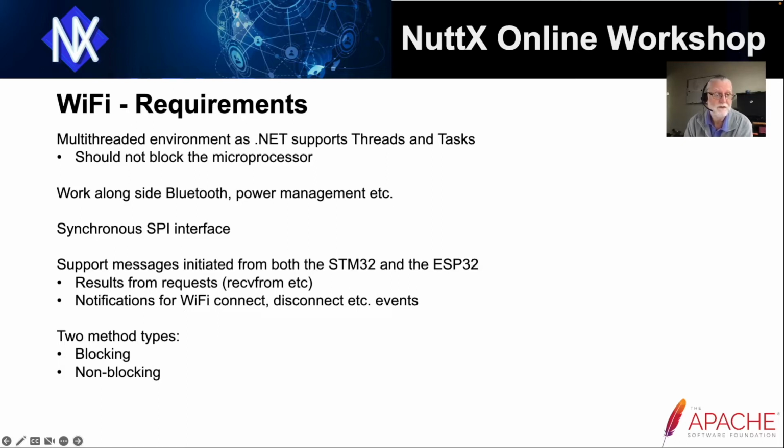We also have a problem we need to consider, that the Wi-Fi could disconnect, or we get connection events, we get disconnection events. Disconnections we have no control over when they happen. So we need some way of getting those events from the ESP32 back to the STM32.